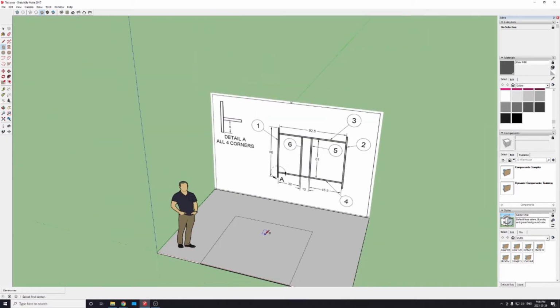So we'll hit Control Z and create another rectangle. I can make this 2 feet by using just a single apostrophe: 2 apostrophe, then comma, 2 apostrophe. The comma just separates your length and your width dimensions. So this will give us a 2 foot by 2 foot box.